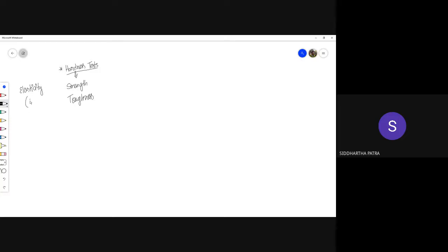which is measured with Young's modulus, which is essentially the resistance to elastic strain for a given load or given stress within the elastic limit. Now we are talking beyond the elastic limit, and if we go beyond the elastic limit, then these are the properties that become significant.